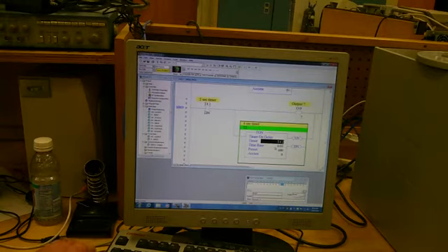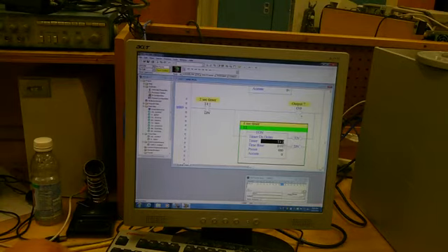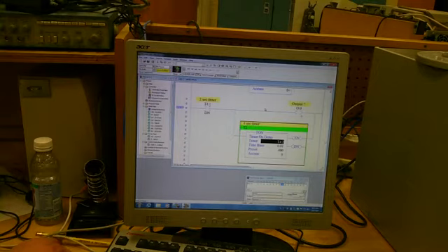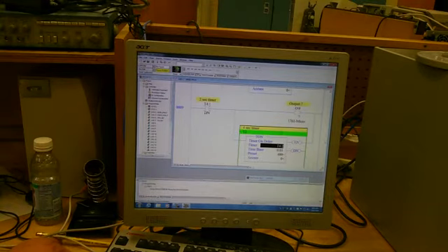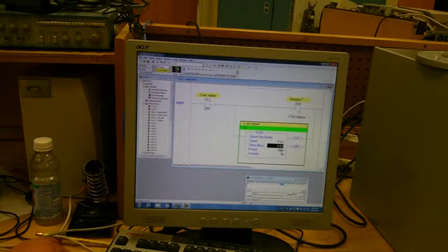Why did you do that? Do what? Take the time base down to hundredths. Because why do the same thing over and over again the same way? That doesn't make any sense, right? So we can use a hundredths time base. Now we can't use the thousandth. It says we have a thousandth one, but in the MicroLogic 1000 there isn't such a thing. So that would come up as an error.